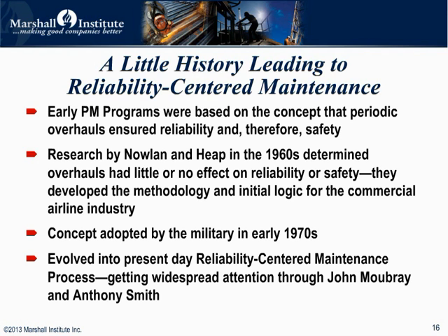Despite this previously commonly held view, the results seem to tell a different story. In far too many instances, PM seemed to have no beneficial effects. Indeed, in many cases, PM actually made things worse by providing more opportunity for maintenance-induced failures. RCM comes out of research in the 60s, which showed that not all failures were age-related or service-related, and because of that, overhauls, which were thought to ensure reliability, did nothing of the kind. PM often seemed to have no effect at all, and overhauls had no effect on reliability, and in fact, were found to actually decrease reliability.